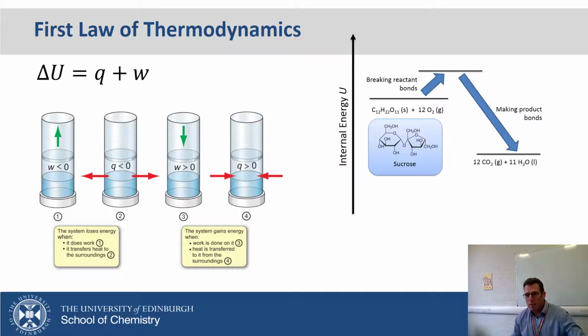So what we've been saying is we can very easily work out the work, heat expansion or contraction. We can very easily work out the heat gain or loss. So therefore we can very easily work out the change in internal energy. And we mentioned that we ascribe signs to these. Work and heat are negative if energy is leaving the system.